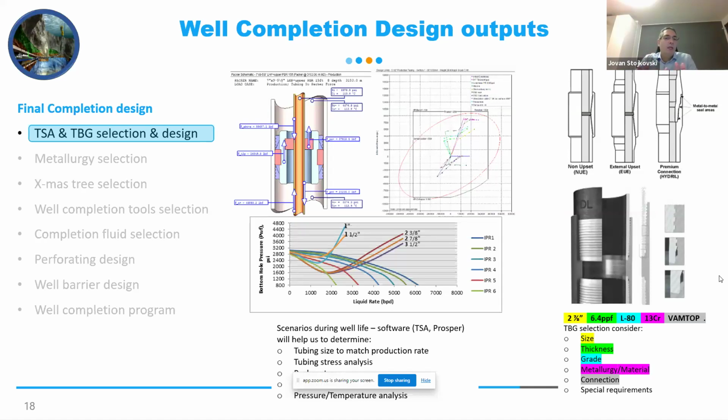You simulate the well during running the completion in hole, pressure testing the tubing, pressure testing the annulus, a possible leak in the annulus, tubing evacuation scenario, stimulation if you have any, killing the well in case you need to kill it, and so on. So many different scenarios, and then you stress your selected completion and tubing and see if everything will work, including the tubing connections.